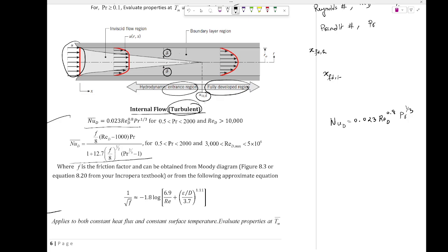And as you look at the other terms of the equation, I don't know if I discourage any of you. Everything else is just the Reynolds, Prandtl, and some other numbers, right? That is a straightforward case. But the F value, as long as you find it from the Moody chart, you're good. Does it make sense? Then you can find the Nusselt number for turbulent internal flow.